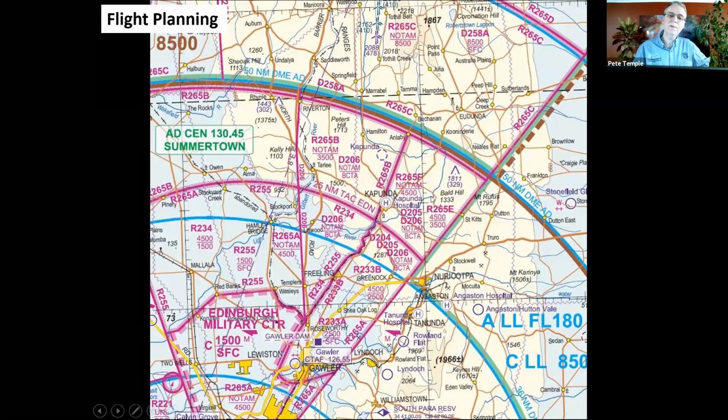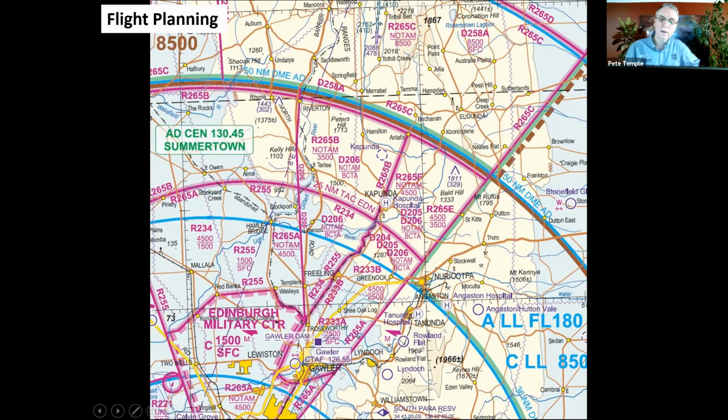And that limits our options, particularly midweek, as this flight was on a Friday. The only real way I could actually get out to start the flight was down this narrow corridor out to the northeast. Out to the east here, we have the Adelaide Hills, which is not something you want to fly over particularly low. And in any case, the thermal activity starts, it takes a bit more time on the plains out to the east here. It takes a bit longer to get going. So early in the day, the thermals weren't starting there. So I was forced to kind of head out to the north.